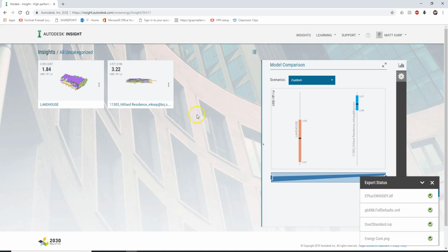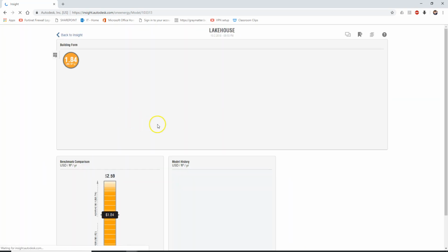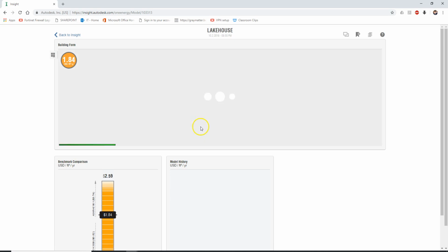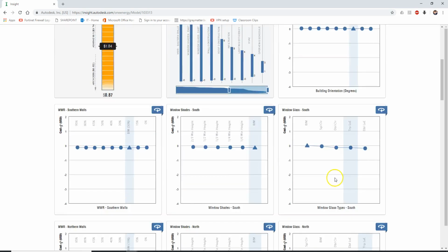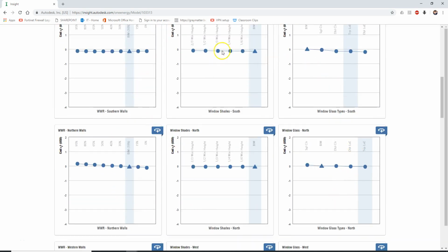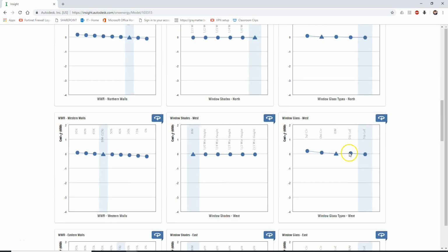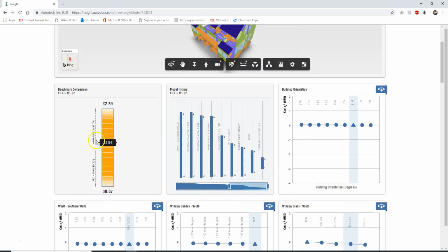And that's the basics. That's the basics of running through Insight 360 and how to take an early Revit model with components built up and test a lot of very conceptual pieces that can reduce energy, to try and get yourself as low as you can in the range you need to be. Obviously, you need to be under ASHRAE 90.1 or you're not meeting energy code, but let's try and beat it as much as possible.